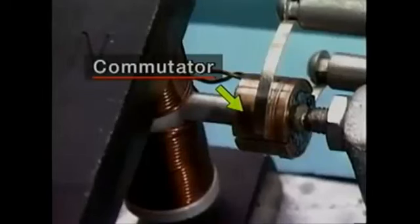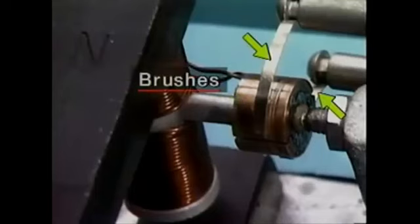When current flows through the rotor's coil, it causes the rotor to become an electromagnet. The attraction and repulsion between the poles of the horseshoe magnet and the poles of the rotor cause the rotor to turn. During operation, the rotor must continuously switch polarity in order to maintain motion. In other words, the north and south poles of the rotor must switch. The parts of the motor that cause the poles to switch are a commutator and brushes. The commutator in this arrangement is a small copper conducting cylinder that is split into two halves. These two contact strips that touch the commutator are the brushes.